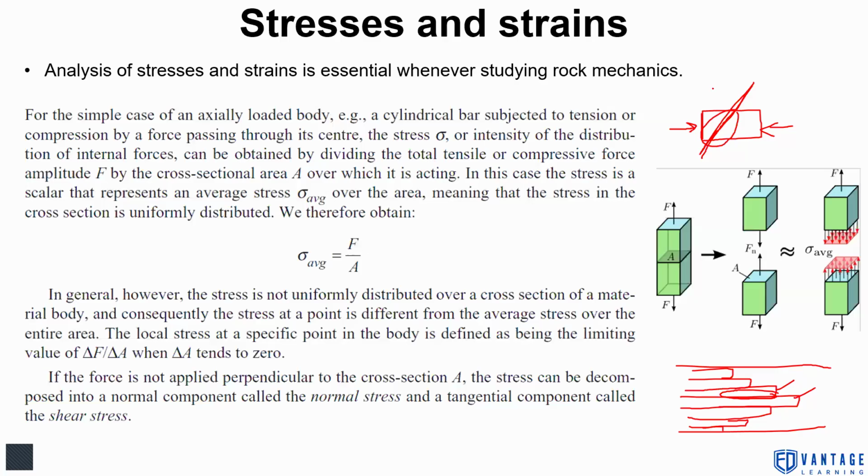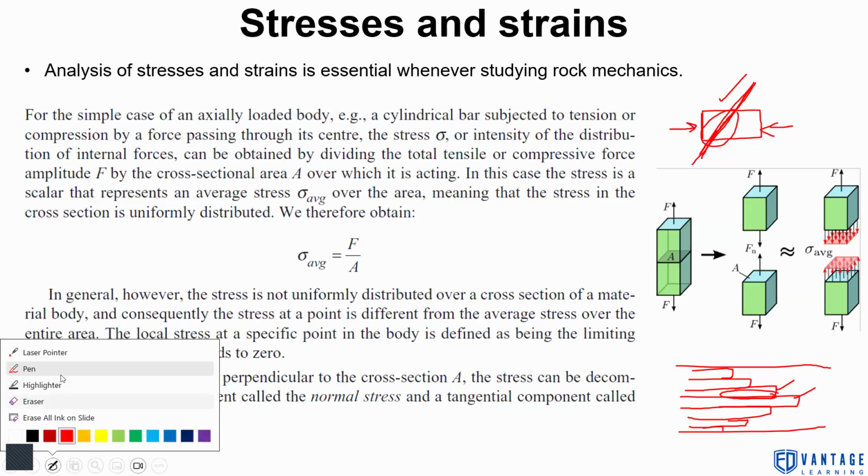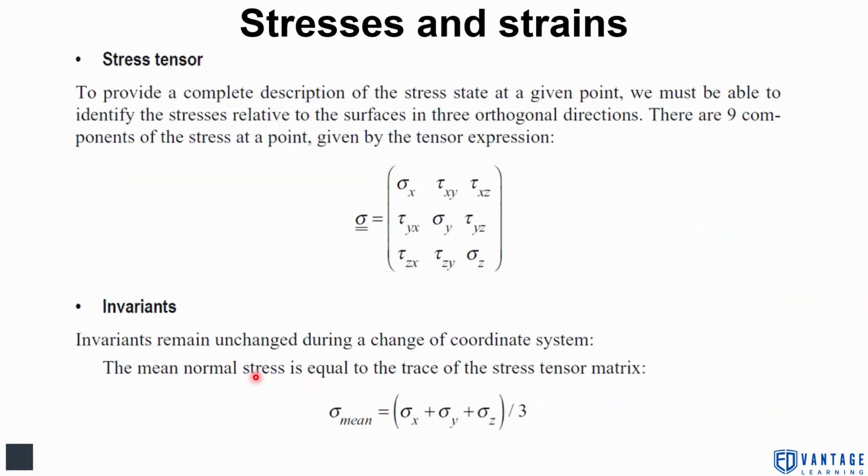When I was doing my very fundamental research on geomechanics, I was from a sand control background. I now work as a reservoir engineer, but my research in my master's and bachelor's was fully on sand control through geomechanics. At that time I discovered that compressional stress will generate shear strain on the block such that the body fails with a shear plane. So it all depends on the body's mechanical or physical nature, to be honest.